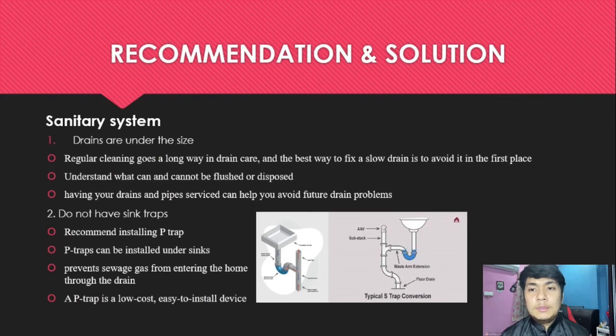Secondly, I will present about the sanitary system. For the first one, the drain is undersized. The way to overcome this matter is regularly cleaning the drains, and people must have common sense about what can or cannot be flushed or disposed.